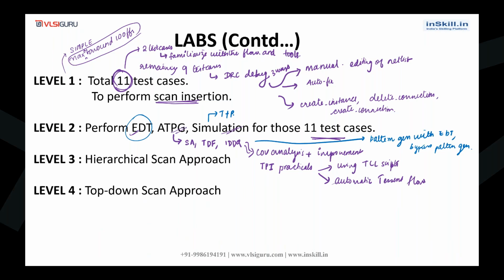And then in the EDT labs we'll be doing the EDT insertion. The EDT components, like the decompressor, compressor, bypass logic, and controller, all those logics have to be inserted into your design. So that is what we will be doing: how to insert that EDT logic into your design. We will also view the EDT logic you have added in the schematic, and in that way correlate what we have learned in the theory and labs.